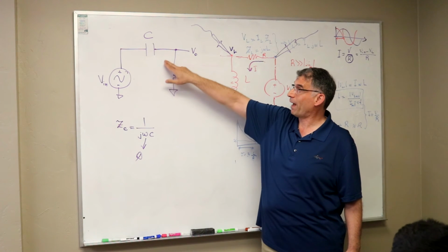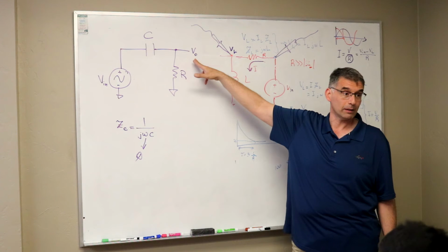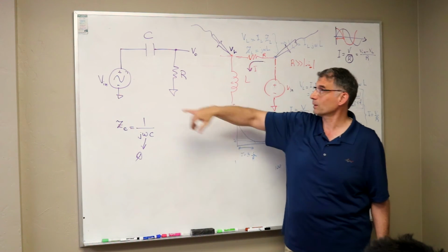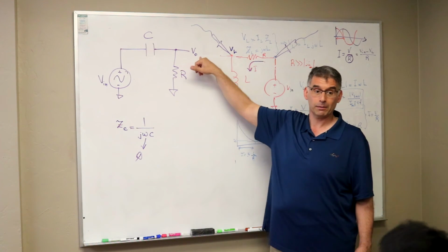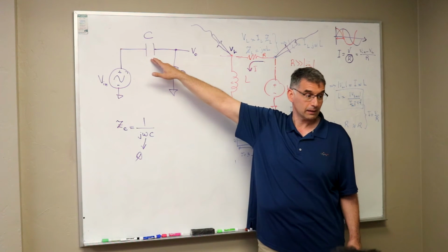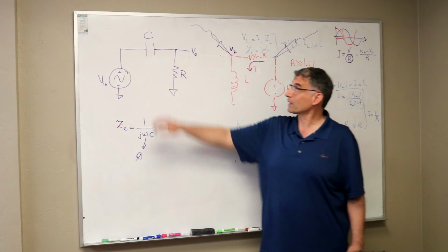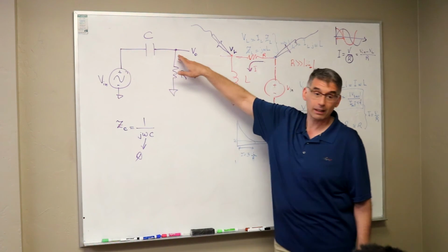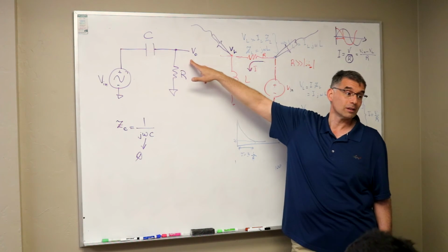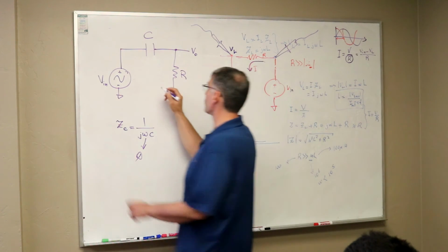If I have a very small current going through this resistor, this voltage is going to be small or large? Small. Small current times the resistance is going to give me small voltage. Now, as the frequency goes up, what happens? It becomes a short. So it's kind of like just putting a wire over here, so the voltage will approach your Vin.